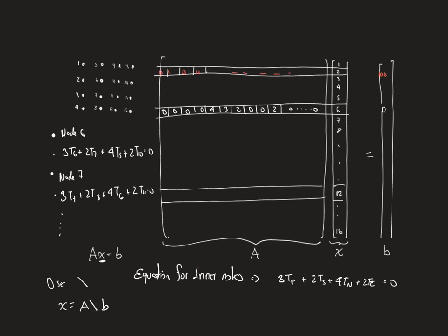When we go to finite volumes, you will see that we can have things that are not cuboids or squares. They are much more free, nothing really standard. So the physical matrix is not really defined, but the computational matrix is always going to be a square, because it's an equation per node.